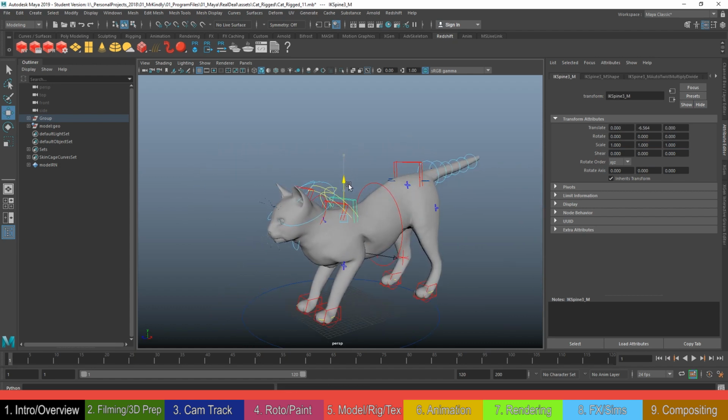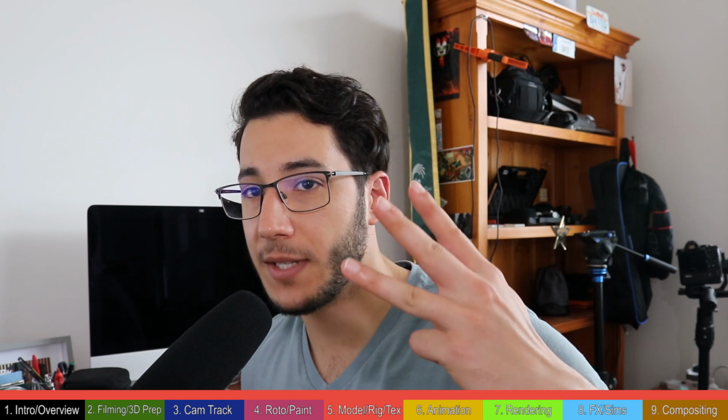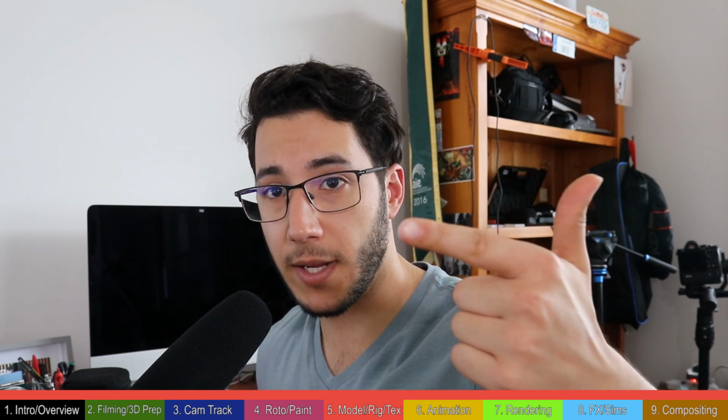Once the cat was deforming nicely, I saved it to its own scene and imported the cat's model into a new scene to make the render model. So by this stage, your one model should have 3 separate saved scenes. Model, rigged, rendered. Model is for building it, rigging is for rigging it, render is for applying the textures.